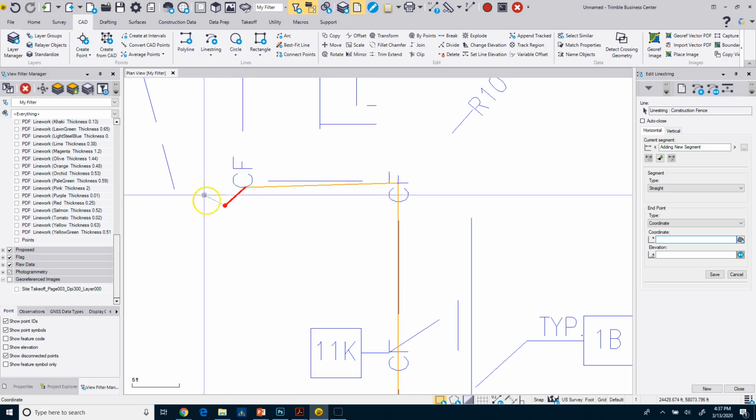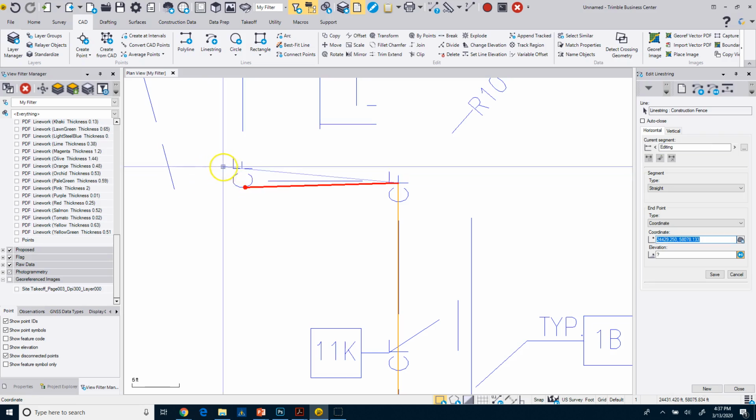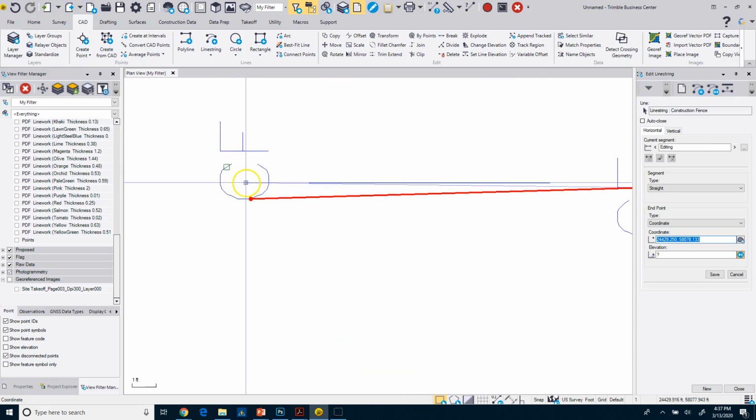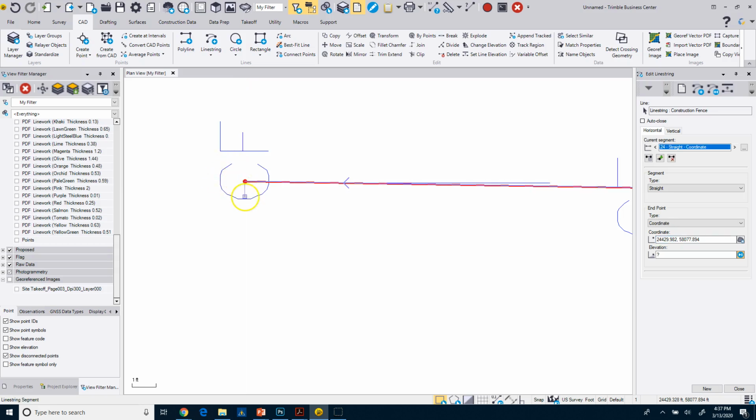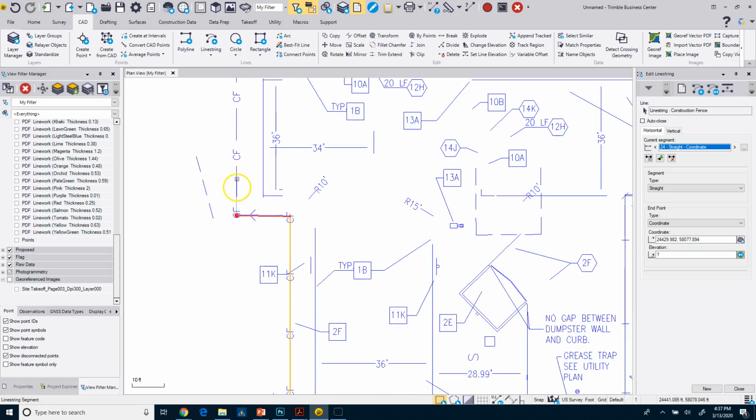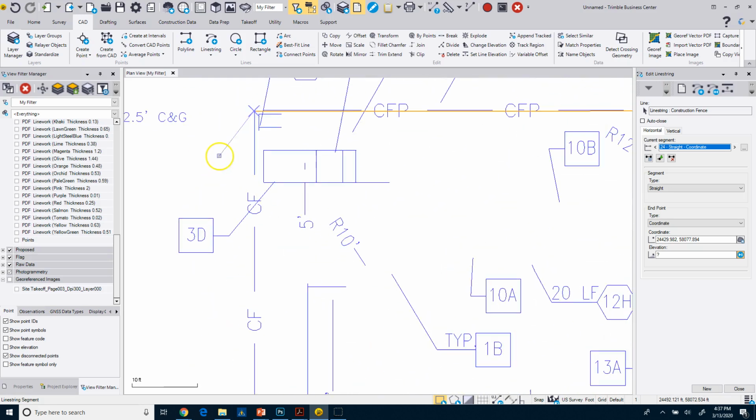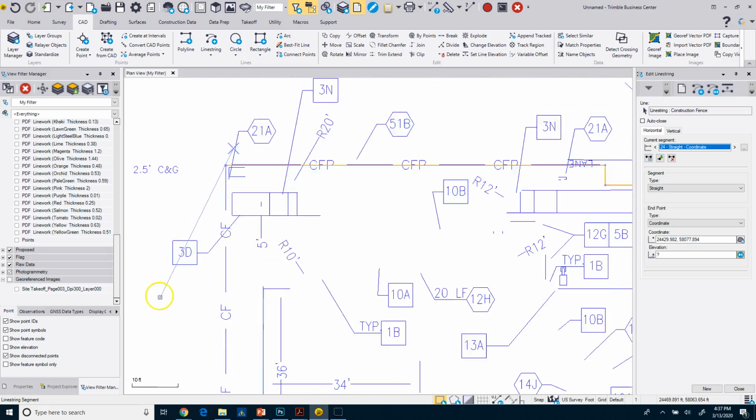You can see I messed up again. Oops. So I'm going to hit cancel, and what I can do now is delete that segment. If I click on this, it removes the current segment. The current segment is the one that's red. Now I remove that, and I can edit this. I'm going to left click to move it, and I'm going to pick a point here, making sure that I don't have any orange glyphs. Okay, and then I can come up and close it.